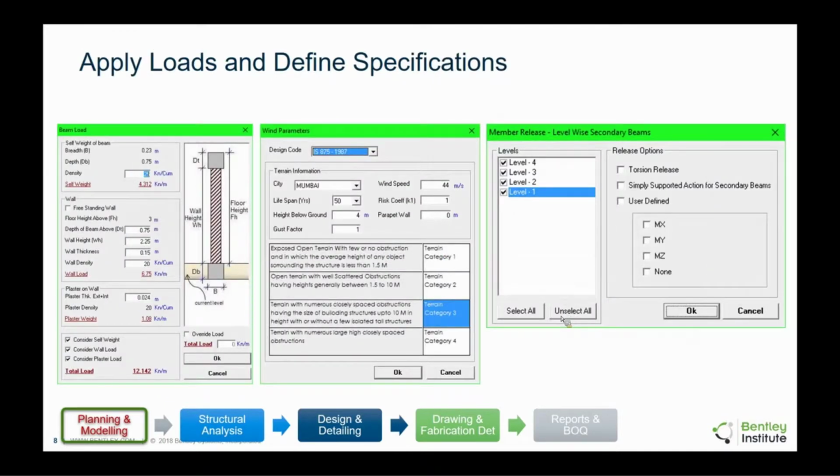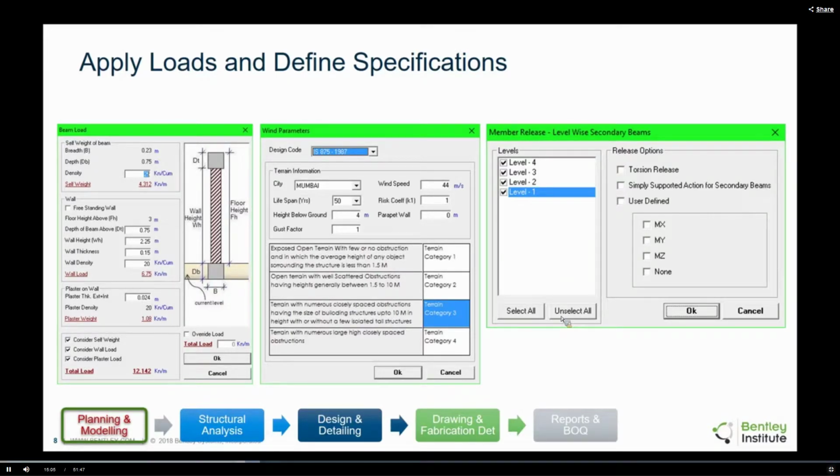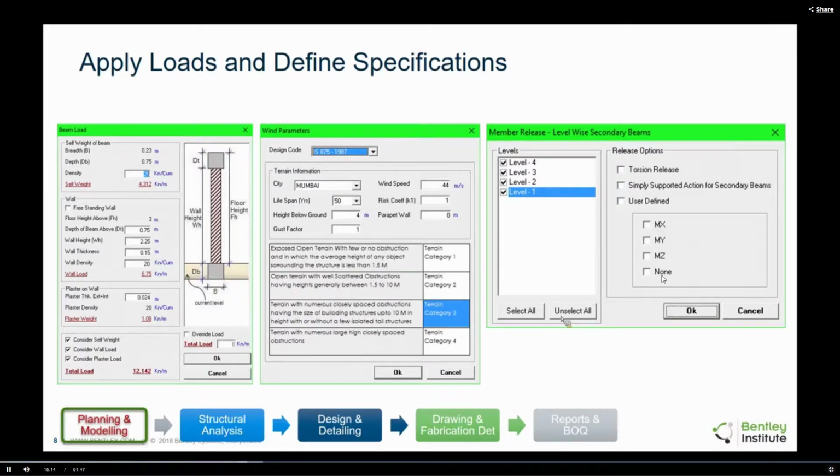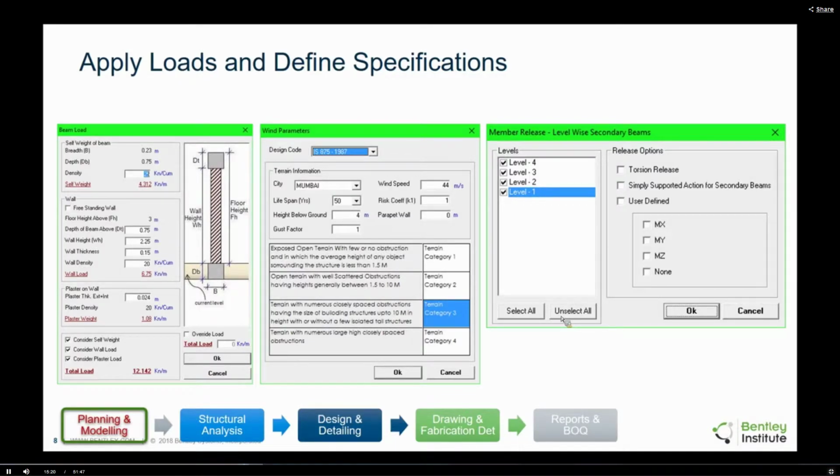So if I'm applying lateral loads, or doing something very interesting, let's say releases. In my typical project, I'm going to have a lot of simply supported beams. So today what I need to do is a STAAD MZ release. Let's say I've got 25 beams per floor, and I've got say 10 floors, I have 250 beams. I missed that setting in a few beams, and I will never figure out that I missed them. Very, very difficult.